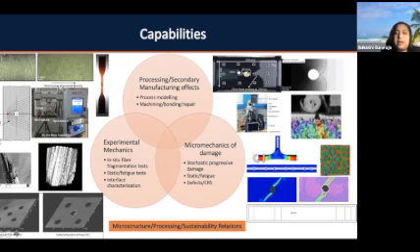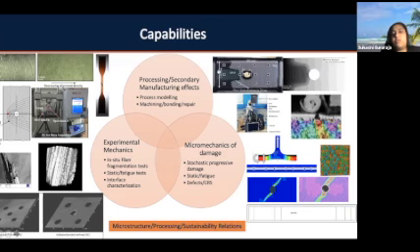And the green fishnet kind of material that you see here is essentially called the high permeability medium. So in these kinds of processes, the typical approach is you would have a high permeability medium, a layer that would be kept on top of your porous preform, and the idea is the resin would flow faster in the high permeability medium and seep in along the thickness direction, so that reduces the required time for fill.